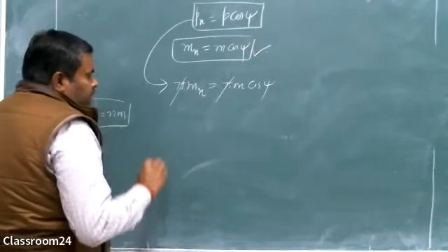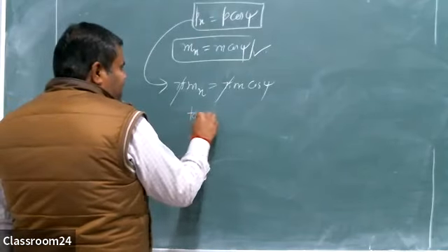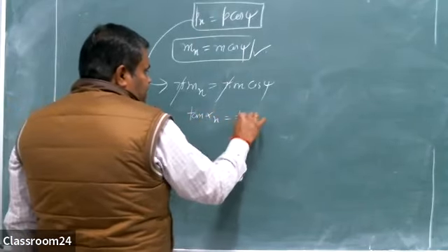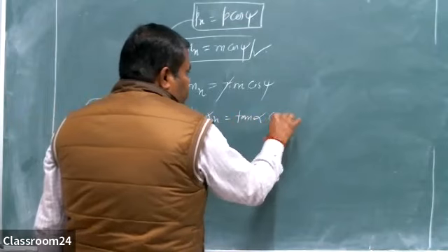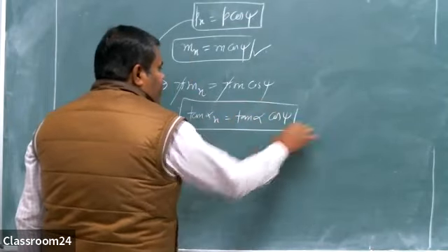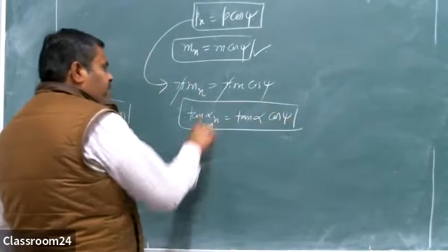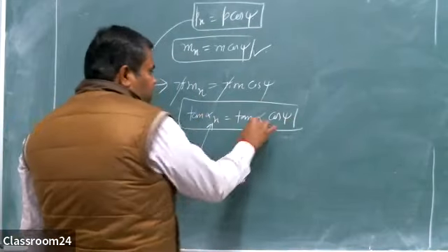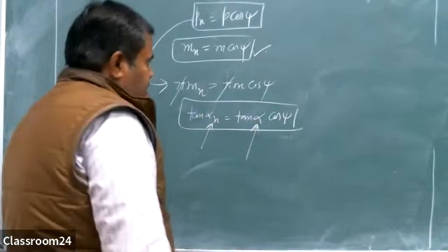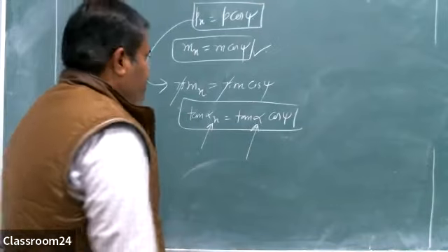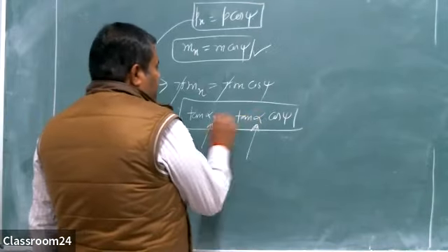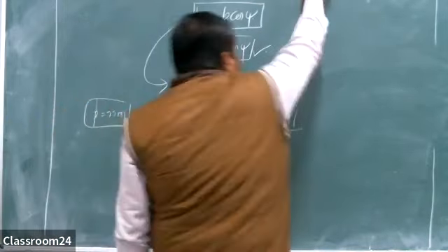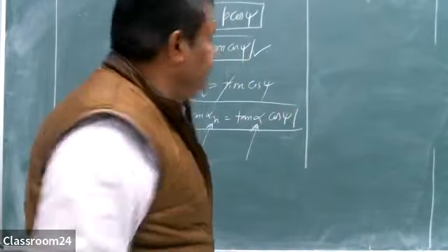Right. Now similarly, tangent of alpha n is tangent of alpha times cos of psi. So alpha n is the pressure angle in the normal direction and alpha is the pressure angle in the transverse direction or in the tangential direction. Now come to the force analysis.